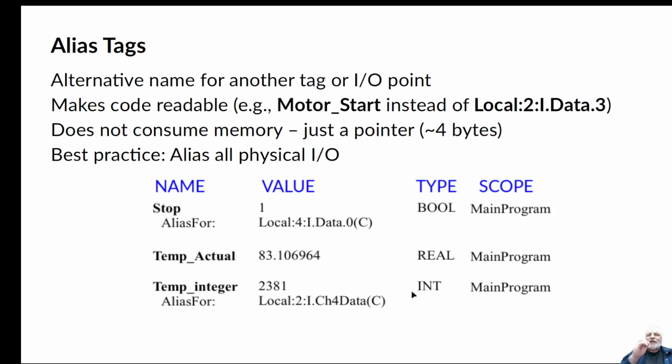So we're looking at channel 4 input, and so what it's doing is it's reading a physical voltage from a temperature sensor, and then that is getting converted into a binary value, which I like to call a count. And so the current count is 2,381.